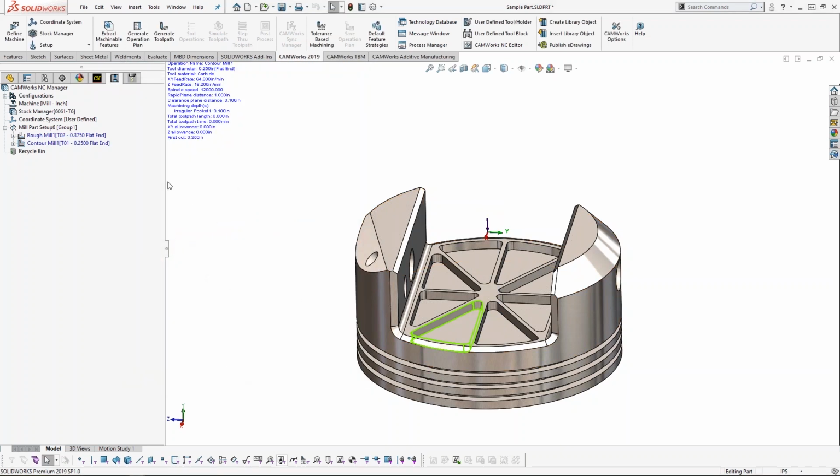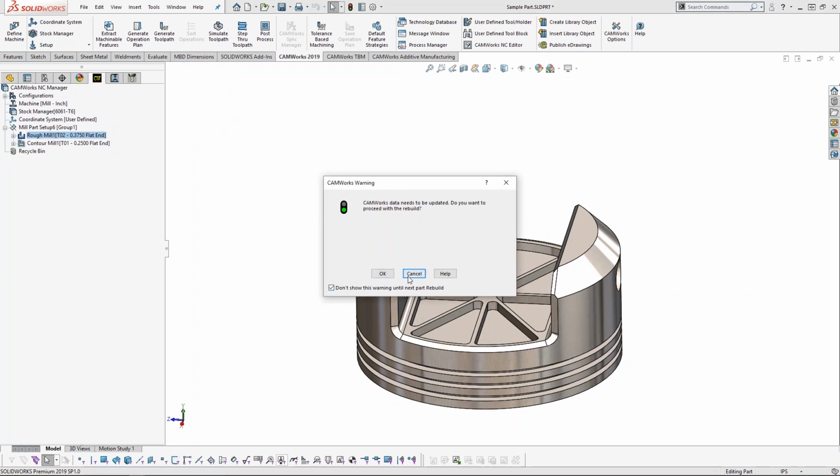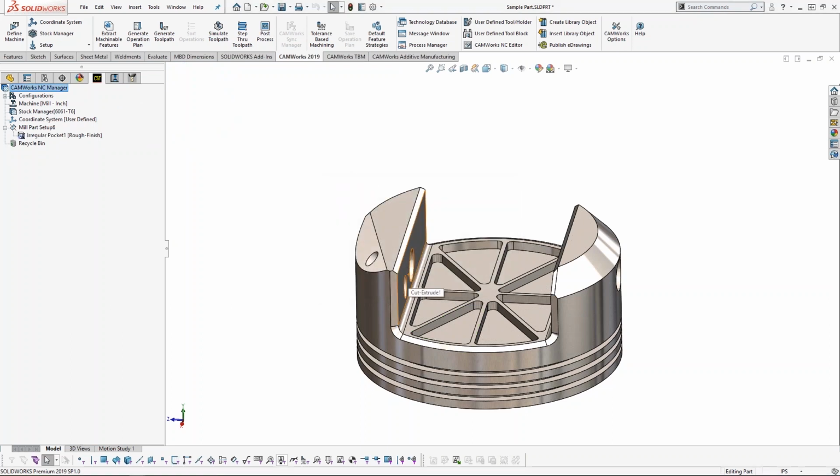But now I have operations. So I have a direction of machining, I have a feature to cut, and I have some operations. The last thing to do is just apply the toolpath to the part. This workflow that I just did is the same workflow that you're probably familiar with in an operation-based CAM tool, where everything's sort of manual. We have to choose what to cut. We have to choose our tools, the order of which can kind of go back and forth.